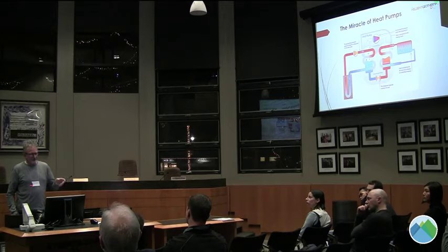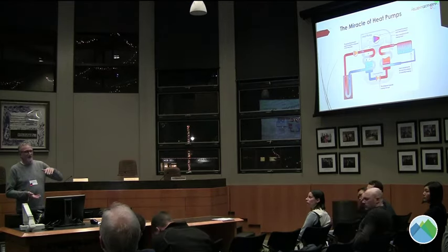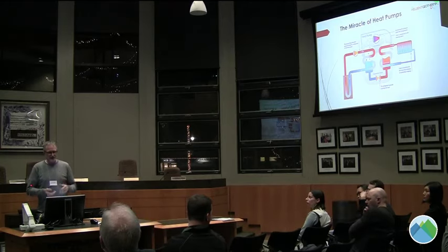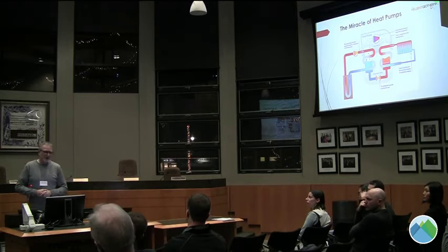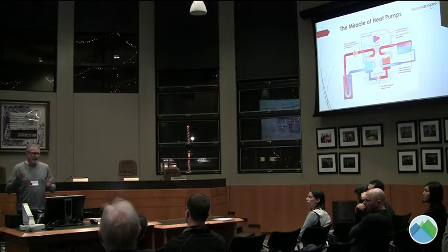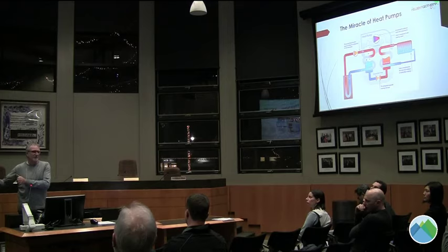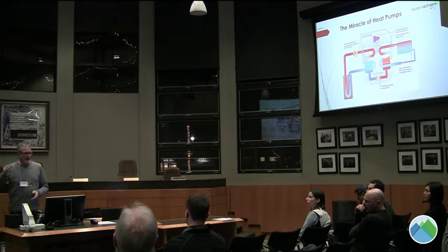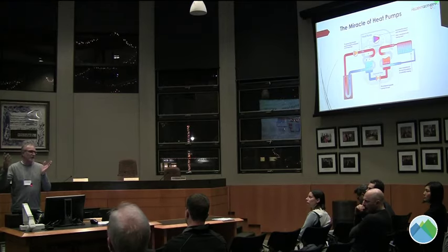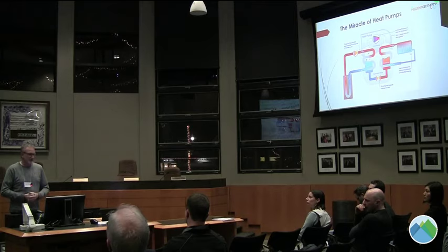and it goes on as a high temperature gas up to the compressor. The compressor compresses, and that enhances the heat again, so that we double up on the heat. At that point, we've got a high pressure, high temperature gas that we condense on the load side, which is the distribution system for the house, and we pull off the heat into either your in-floor or your forced air unit, and the circuit continues.